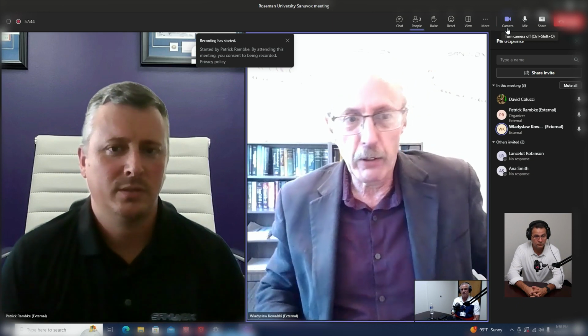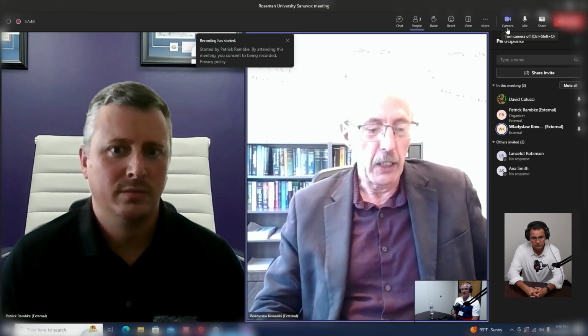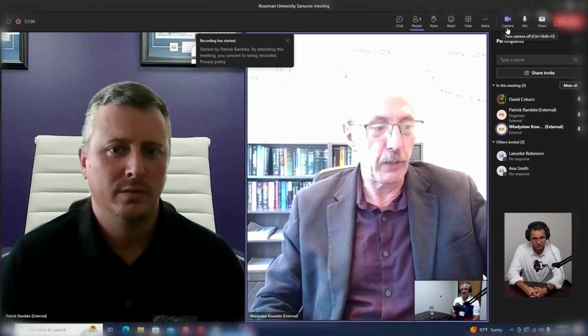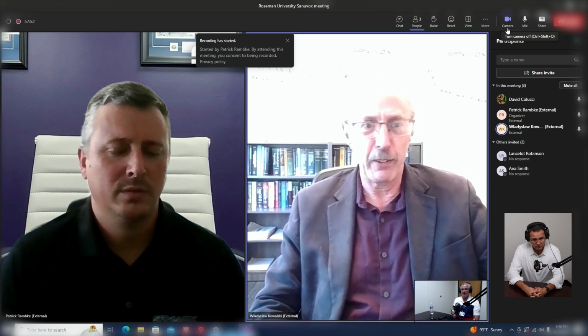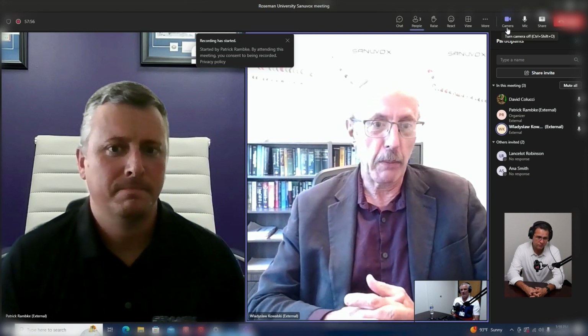ASHRAE does not favor ionization. I don't think most people in the industry do. It's not terribly effective. Even if it's cheap as heck, it's just not very effective. There are other technologies out there which might be effective.